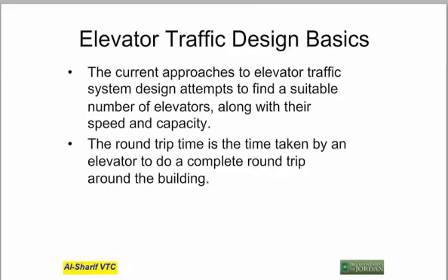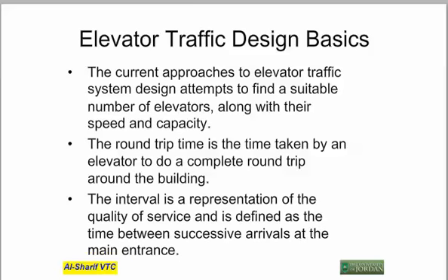And the way the designer will usually go about doing that, the classical way, is to find the round trip time. The round trip time is the time taken by an elevator to do a complete round trip around the building, usually under incoming traffic conditions in the morning up peak. That would be like a cycle time for the elevator, and this is what we usually refer to as the round trip time, or the RTT.